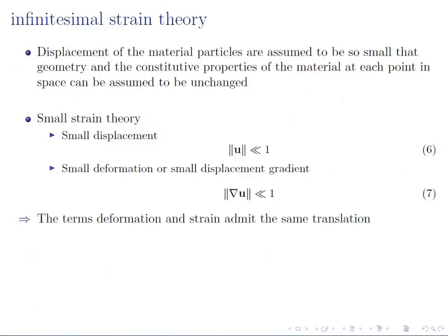Okay, now let's come to the definition of strains, and in this course we will be dealing with infinitesimal strain theory. That is, we will not be dealing with large deformation, large displacement of the bodies in this course. According to the infinitesimal strain theory, displacement of the material particles are assumed to be so small that the geometry and the constitutive properties, both of them, of the material at each point in the space are assumed to be unchanged. Accordingly, infinitesimal strain theory assumes that the displacement of the bodies are very, very small.